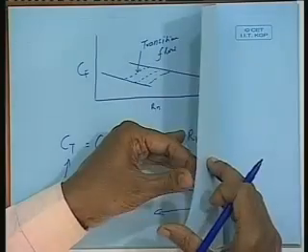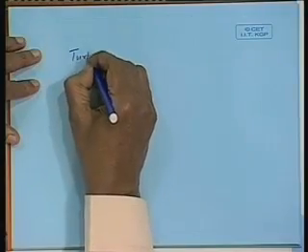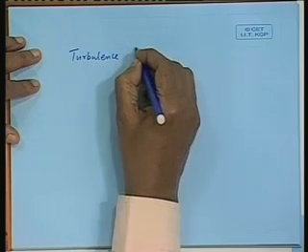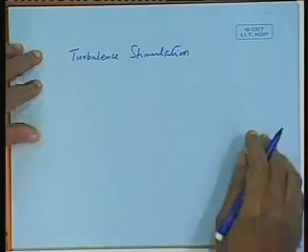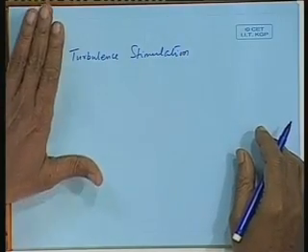So, use turbulence stimulators. Turbulence has to be stimulated. We have to stimulate turbulence in the fore part of the ship. And how do you do it? We will have to introduce artificial roughness at the front end of the ship, so that the flow becomes turbulent because of the existence of a rough surface, as if we are introducing forcible turbulence on the ship forebody.